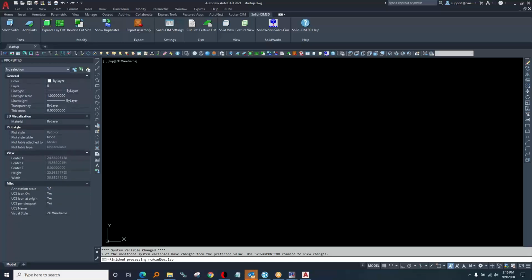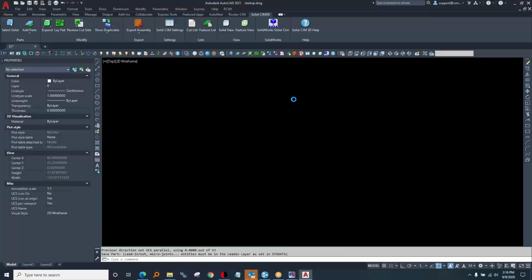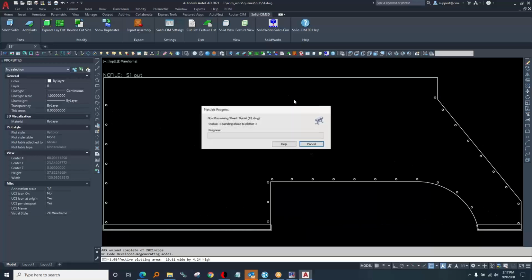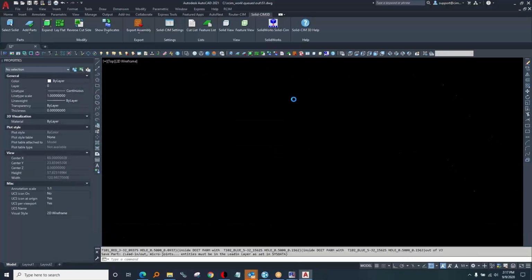You saw layer names on the geometry like pocket cut and cutout, hole. Those layer names are associated with different machining operations we have set up in a template file. And now there they are applied. So there's a pocketing getting cut, the outside's getting cut, the holes are getting marked, and then they're sequenced together by a closest point. We have a rank sorting method. You could set up your machining operations to sort by a rank number.